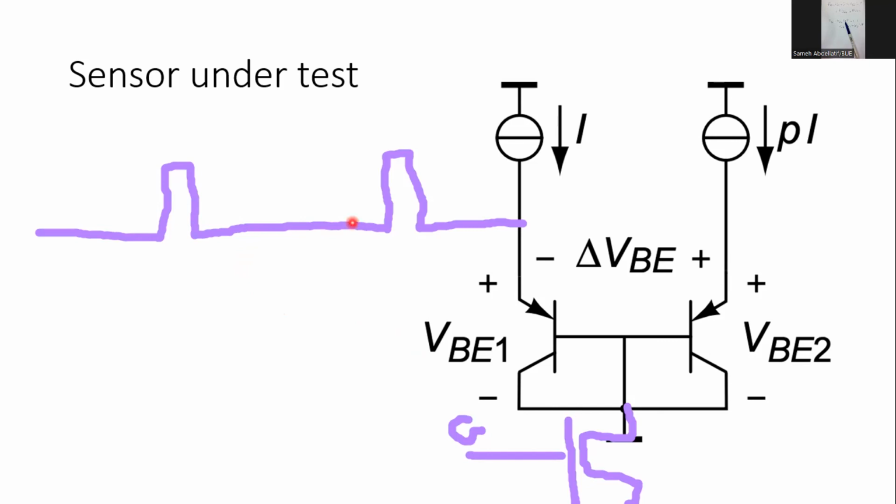Of course, you should act towards choosing MOSFETs with maximum on-off current ratio, or in other words, with minimum off current, so that you can minimize the power dissipated in the sleep mode. But practically speaking, you have to consider that there is still some power dissipated in the sleep mode. Of course, it's much lower than the power dissipated in the active mode, but it should be considered, as you have a long interval of sleep mode. So even with a low power, this accumulates into energy.